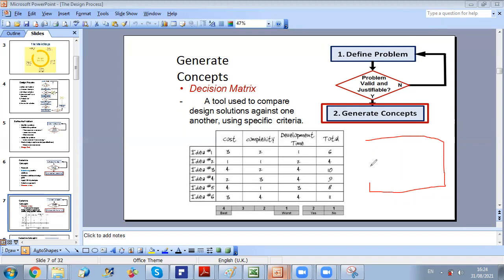What is personalized ventilation? So for each person, I can put in front of it a small device that will give it a small amount of fresh air, okay? And in this way, we can first reduce a lot the energy consumption because in mixing ventilation, you are cooling the whole space.